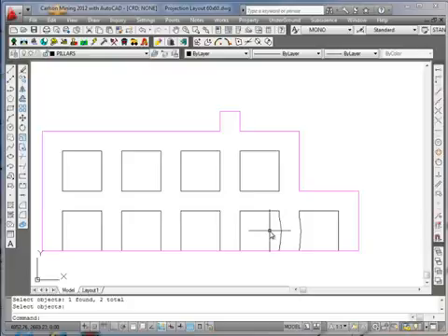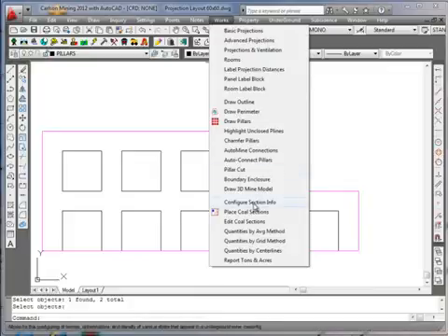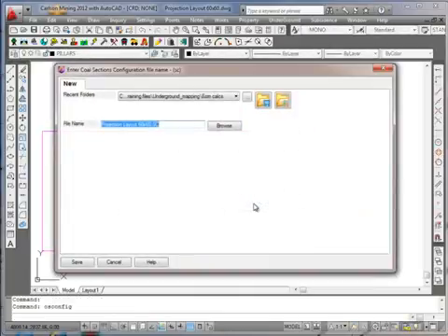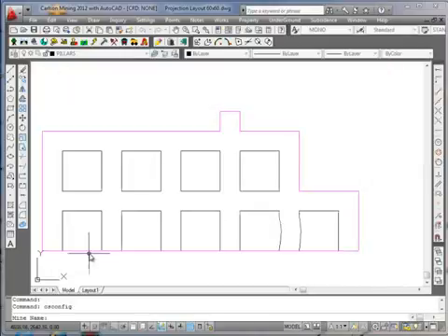The next thing we'll do will be to build the section configuration file, and that's found under the Works drop down under Configure Section Information. And what we're going to do in this case is, I'll just call it training. We're going to build a series of prompts that allow us to enter the coal sections or the thickness measurements of the rock and the coal as the surveyors would identify them in the mines.